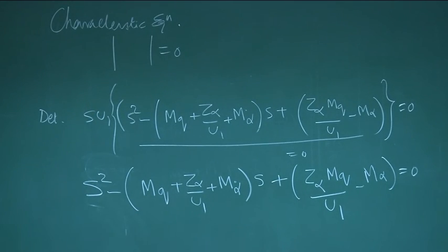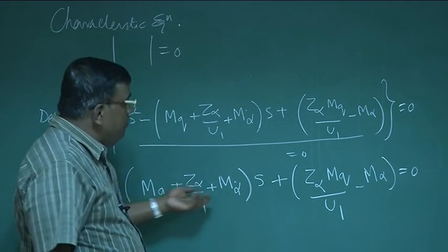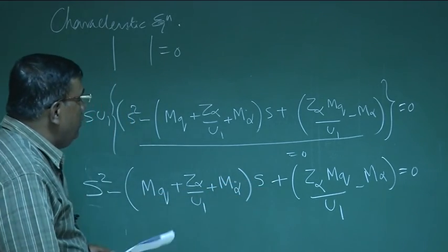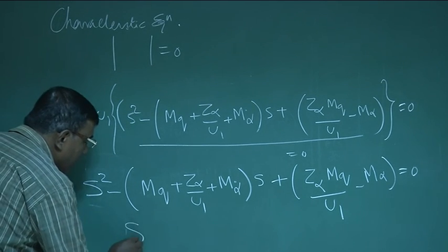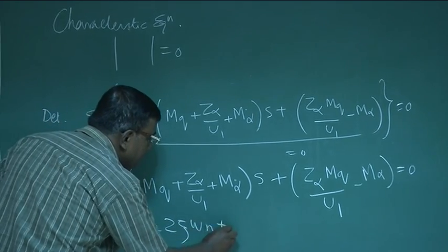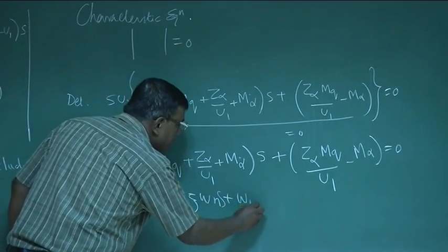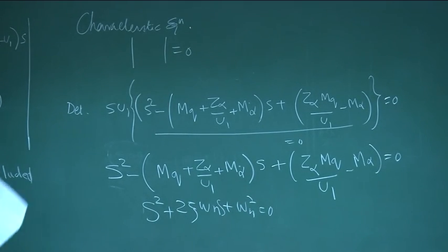But you see that when I do a short period approximation, we have got a second order equation, and we are very much handy in handling this equation because we know if I want to find out the damping ratio and natural frequency, I have to only compare it with this form which we have already derived. So now if I compare, what do I get?